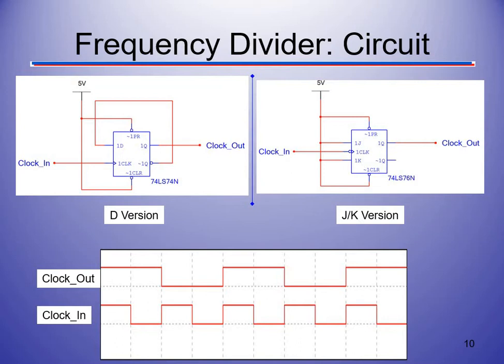Our Q naught becomes our new D. So that's what's going to be our driving force. So when we used Q naught as D, all right, we're using its feedback to replace itself. So when the clock comes in, our divide by 2, notice that the period is twice as long. And then the more we add, all right, and we divide that signal by 2, and then the next signal by 2. Okay, so that's how you set those up.